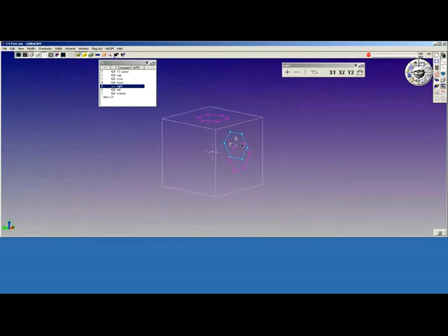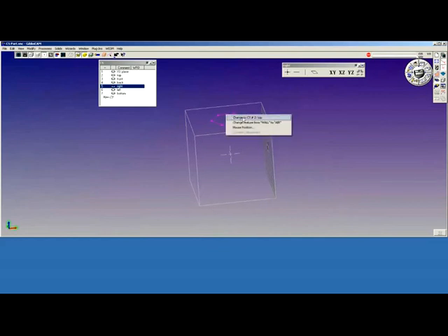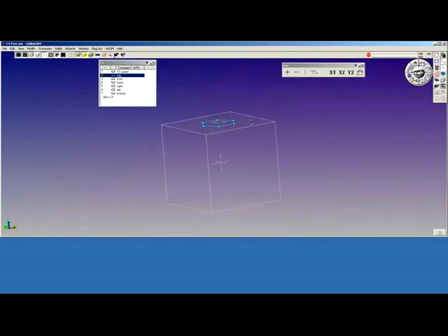Okay, so I'm going to delete these two hexagons. Another method for navigating coordinate systems is if you have magenta geometry, you can right mouse click it and change CS, in this case to number 2 at the top. And that's another way to get the coordinate system activated based on the geometry.